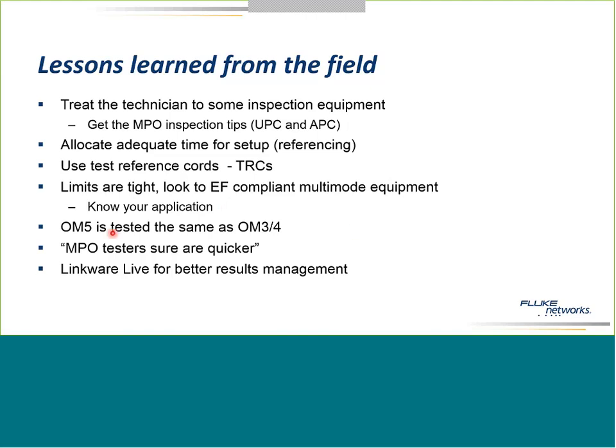Testing OM5, here's the good news. Testing OM5 is the same as OM3. Actually, the limits are the same as OM4. We've got a loss value. We compare that loss value to the application. And the distance limit on OM5, for right now, I'm going to stick with 150 meters. The modal bandwidth of OM5 is the same as OM4. So OM5 isn't giving us any extra distance.